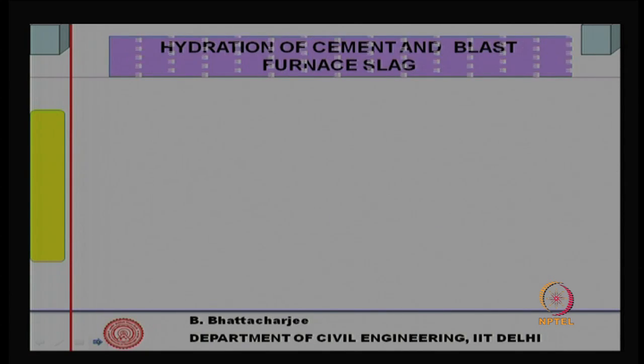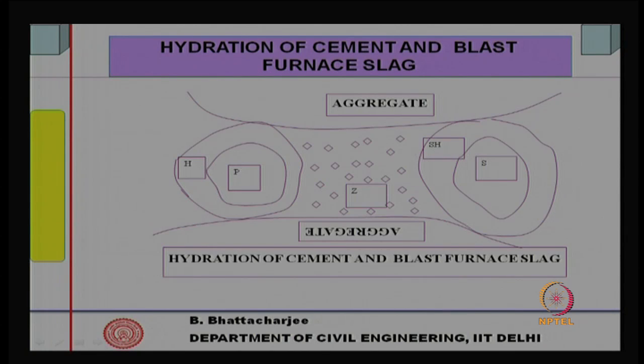But if you look at reaction with slag, this is my Portland pozzolana and this is my slag. Now, slag, remember, has got calcium oxide also. So, it has almost cement-like composition, only thing is it has less calcium oxide. So, it should react with water itself, but it does not, it reacts in presence of an activator. If you can activate the slag, slag will react. Various materials in cement, when it reacts with water, for example gypsum, alkalis, etc., can act as an activator.